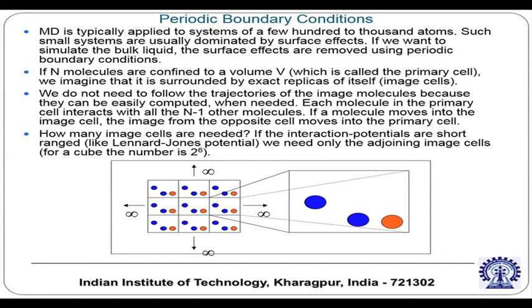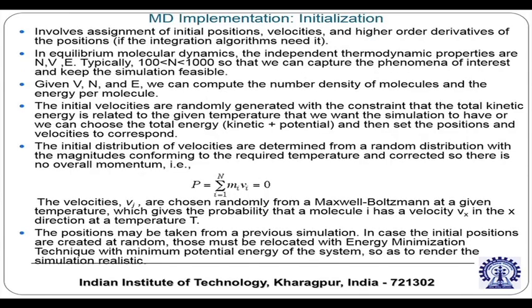So it is basically repetitive behavior of some monoblocks, where each monoblock is a unit cell type of thing, and you basically consider that whatever is the boundary condition at the inlet, for example, at the outlet of the repeating unit the same boundary condition is repeated. So that is called the periodic boundary condition.